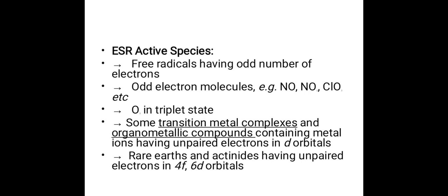It is stabilized against temperature fluctuations by immersion in an oil bath or by forced air cooling. The frequency of the monochromatic radiation is determined by the voltage applied to the klystron. It is kept at a fixed frequency by an automated control circuit and provides a power output of about 300 milliwatts.